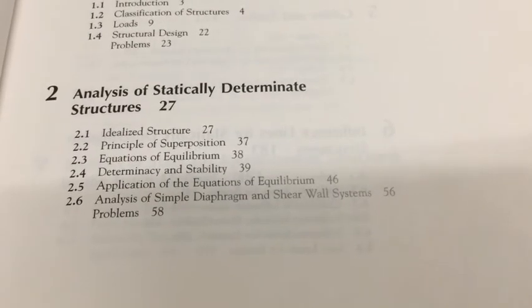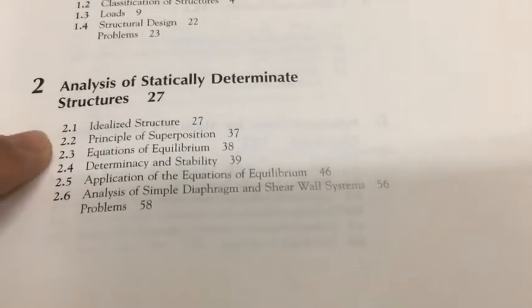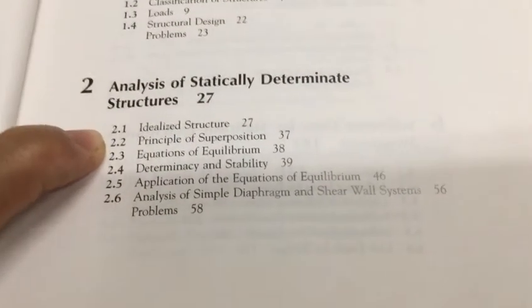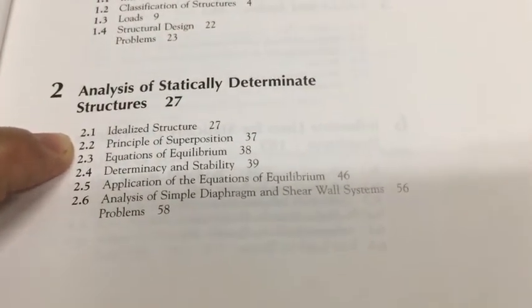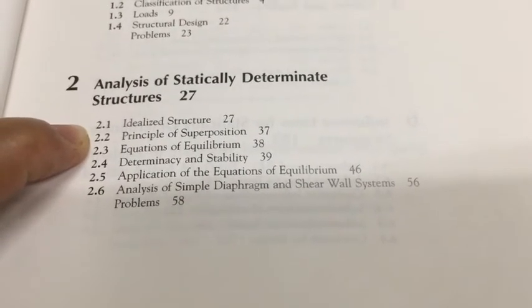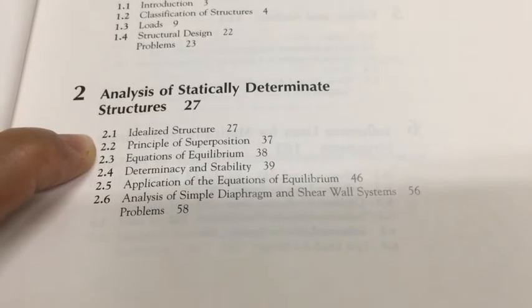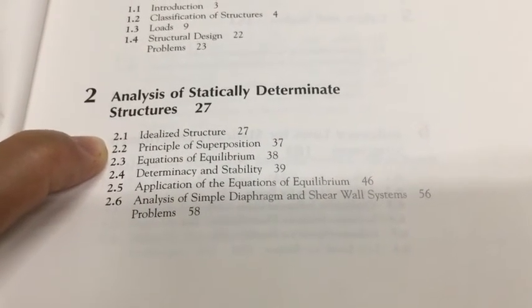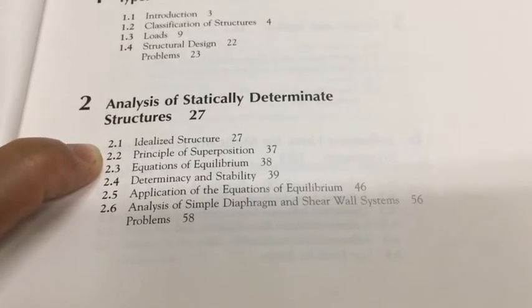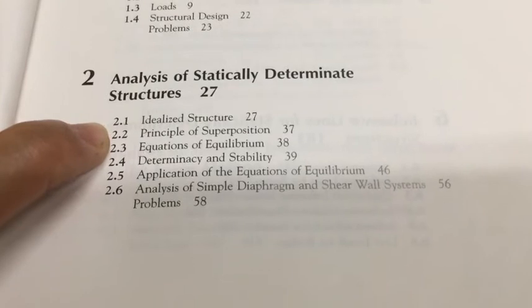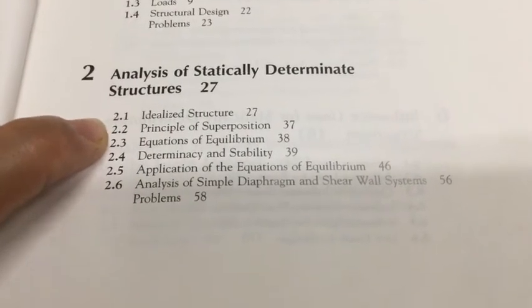We would like to find the maximum deflection of the beam on the examination, and then we can find the total deflection by finding the reaction from the 2 separate beams. And finally, we use the principle of superposition to combine them.